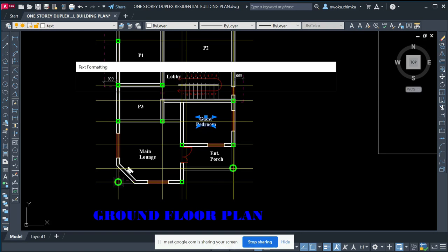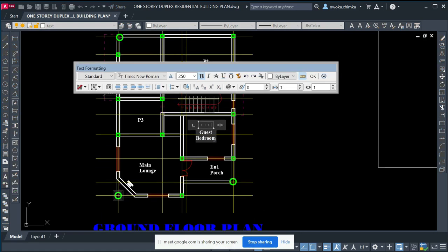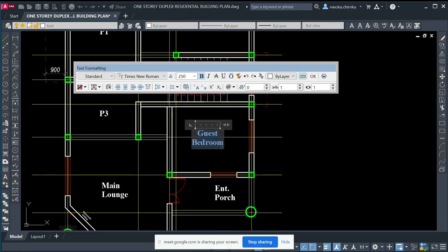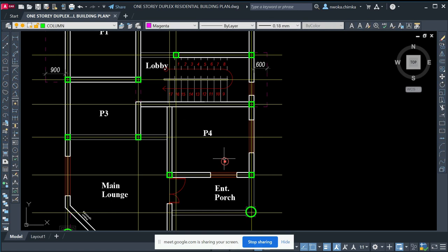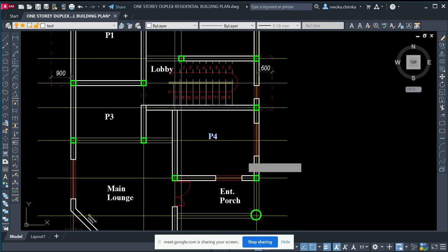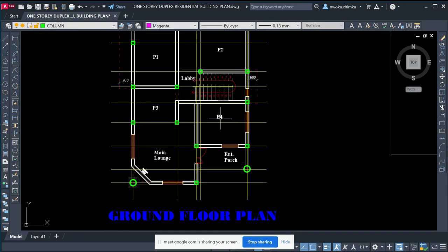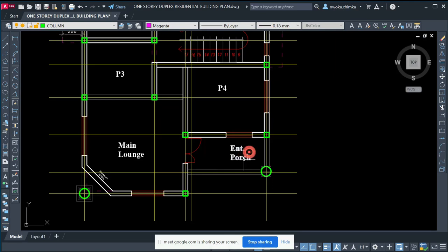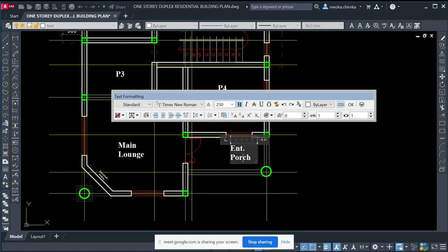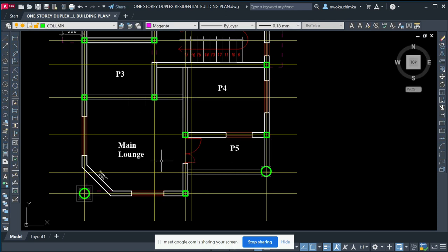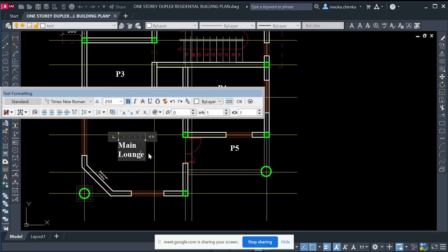Okay, so those internal beams will be carried by those other beams. Yes, you'd also have to check if those beams that are carrying the internal beams are going to be able to carry the load, or you'd have to put some columns on the intersections if necessary. That's true.